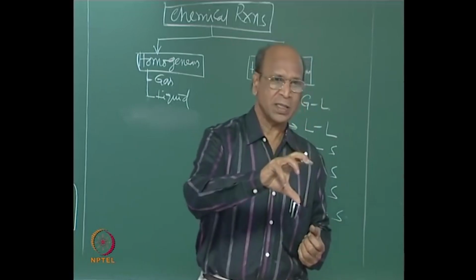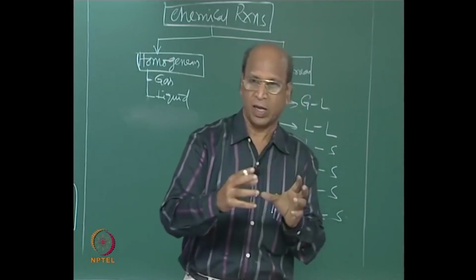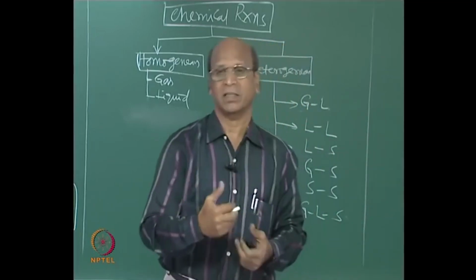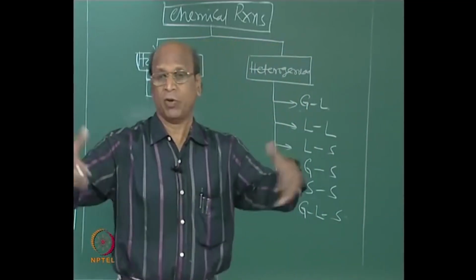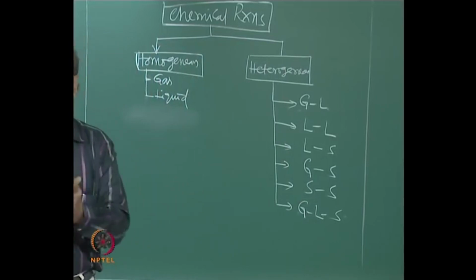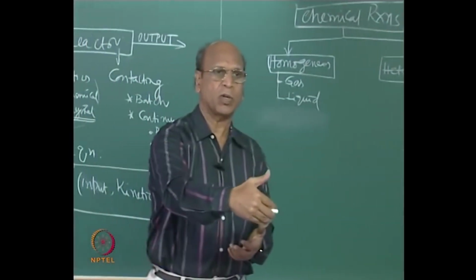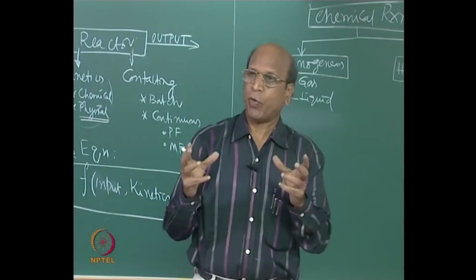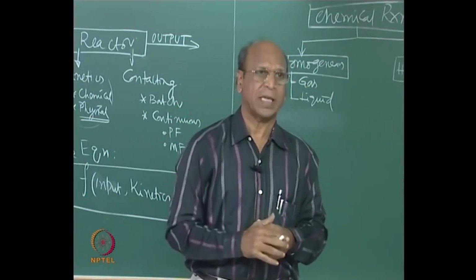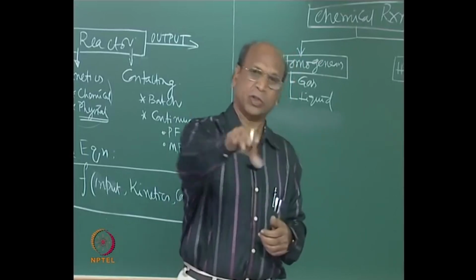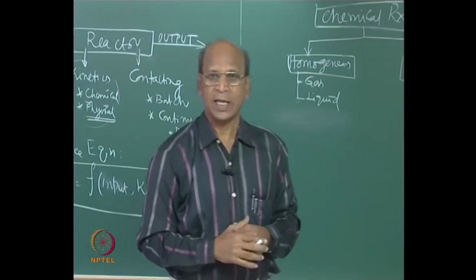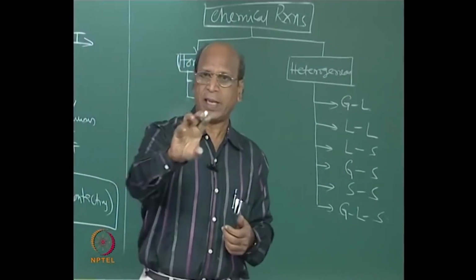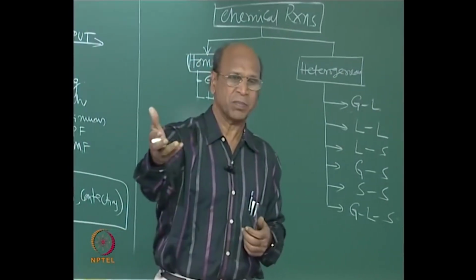It should be porous, but the pores should be sufficiently large. It should give sufficient surface area, but less resistance. That is why we have that idea of effectiveness factor. You manufacture a catalyst and then try to find out what the effectiveness factor of the catalyst is. If I say that I have only 50%, that is 0.5 effectiveness factor, we are talking about isothermal. Non-isothermal, it will go much higher. Because same definition, you said: the rate of reaction divided by the rate at bulk conditions, right.